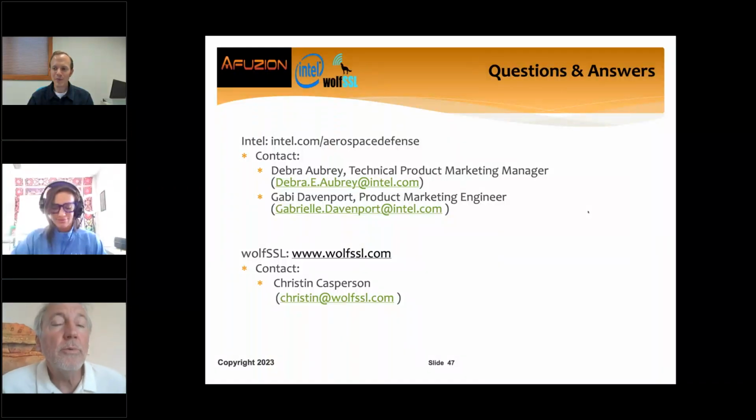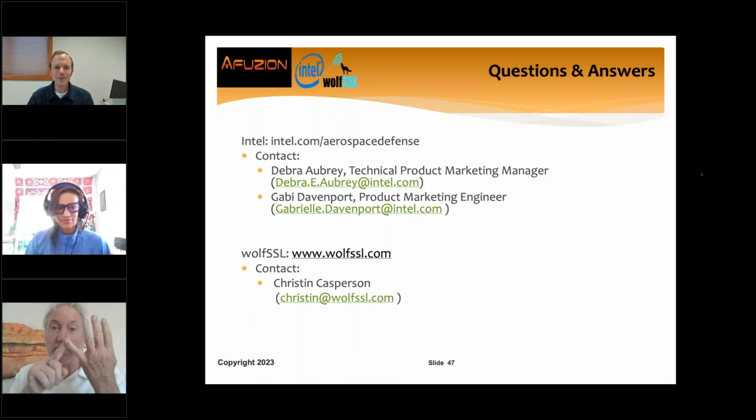Great answer. And folks, remember, AC 20-152A or AMC 20-152A over in Europe, that's the fifth and final, well, we think, until the next final interpretation of DO-254. It's not like 178, okay? 178 is self-contained. There are 4 versions. You're using 178C now for all new products. You don't ever have to open 178B, the 3rd version, unless you have a legacy product. Remember, 178, 1980. 178A, a few years later. 178B, 8 years later. 178C, ooh, 15 years. So it's self-contained.